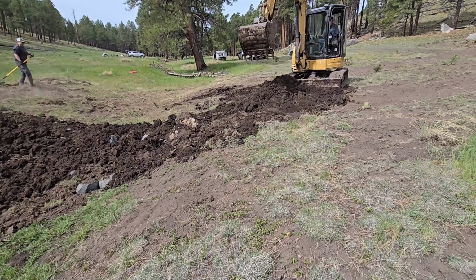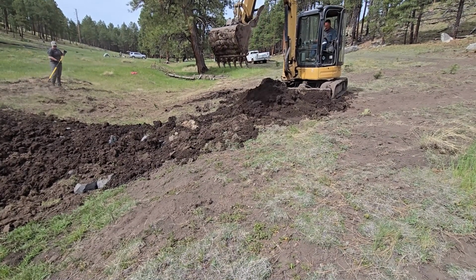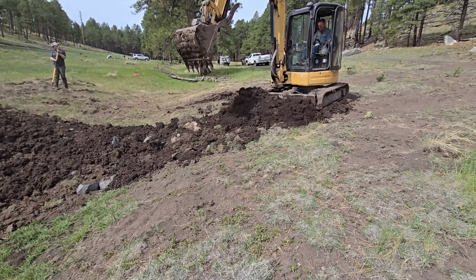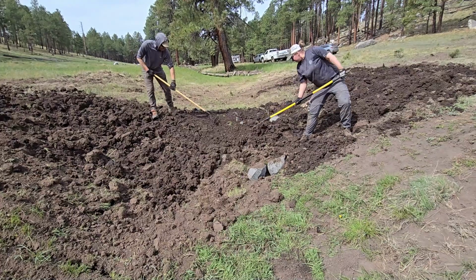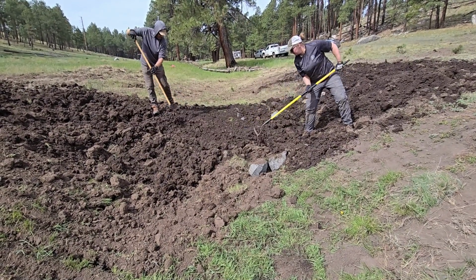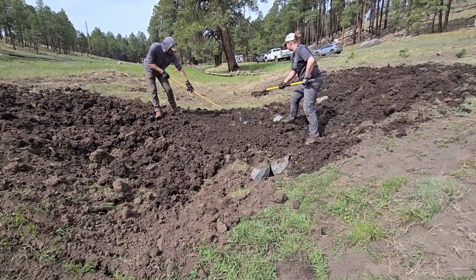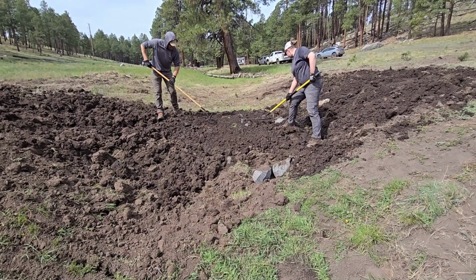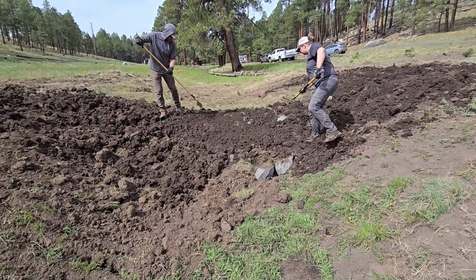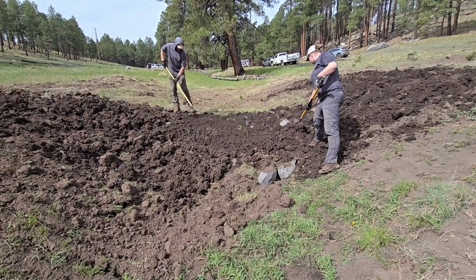Don uses the blade on the excavator to spread the remaining soil that was removed when the trench was dug for the rock. He is also spreading soil over the rock to hide the rock from view so the valley will look natural. The crew uses rakes to fill voids between the rocks with soil and to break up large clumps of soil. The hand raking is important because the surface of the ground can be adjusted so that water flows over the rocks in a sheet-like pattern and does not cause erosion. The project turned out better because of the final landscaping that was done by hand.